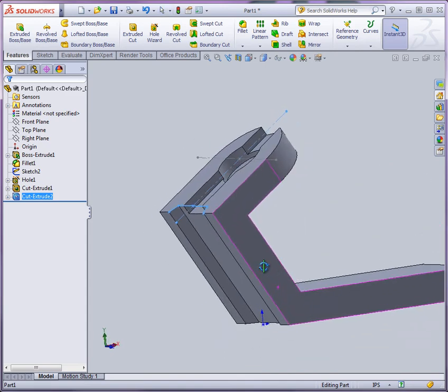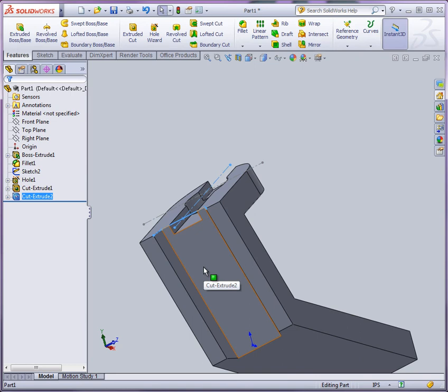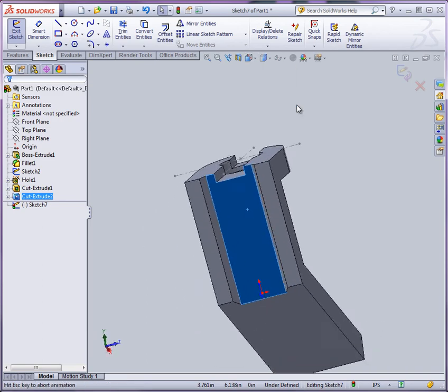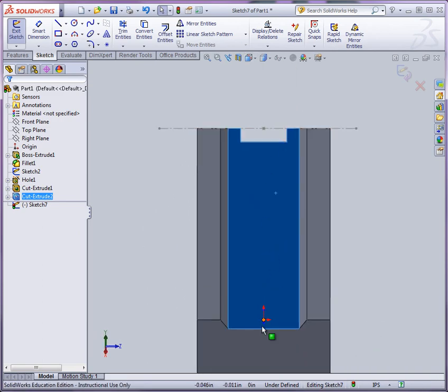All right, let's finish up with auxiliary face B here. We've got a couple holes that we want to draw in. So what we'll do is we'll select the face, create a new sketch, and then make sure the face is selected and go normal, right? Here again, you can see I have the sketch origin.